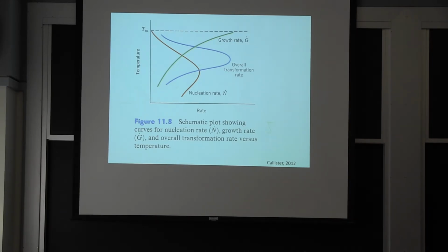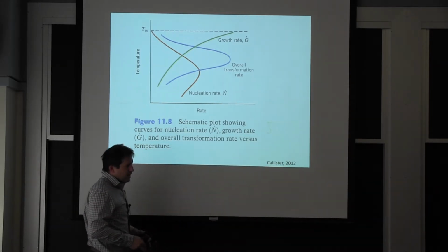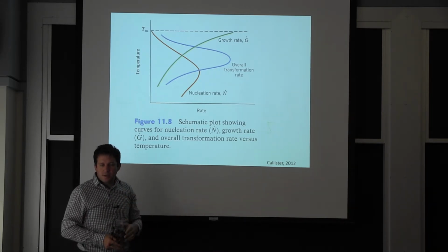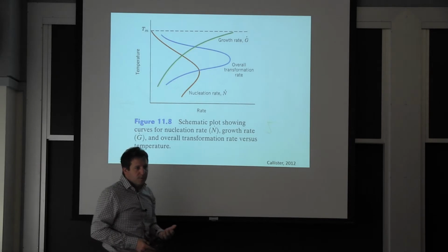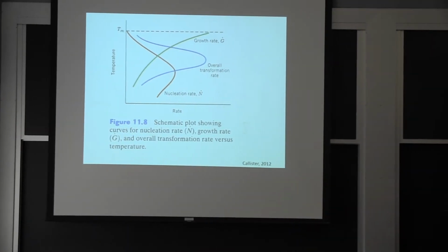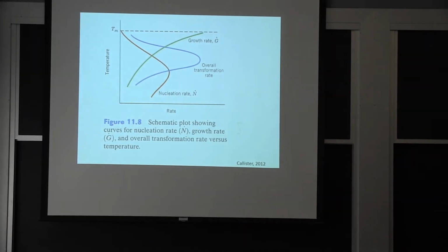The spacing of these laminar structures is going to be much bigger at higher temperature, and that's why at the end of last class I showed you the nice pearlite structure with the different layers, because it was oven cooled, which is not typical. Typically you take the piece of steel out of the oven and it gets air cooled and you get a finer microstructure. But if you go more quickly, you can essentially adjust that spacing and the strength of the pearlite.